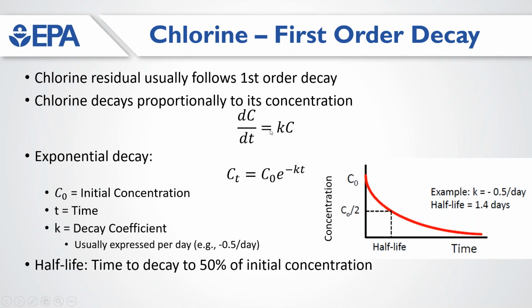Likely, first order decay is not what your data tell you. Then you can try second order or zero order to see what happened. If none of them work, probably this single species model is not a fit, so we need to think about something more advanced. But usually people in reality just use the first order model, even if the model doesn't fit their data set well, because it's built into EPANET and convenient to use.